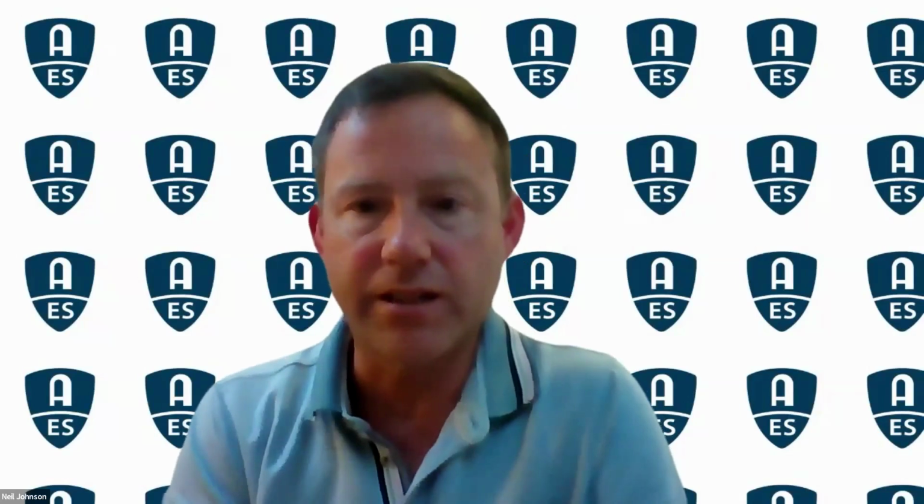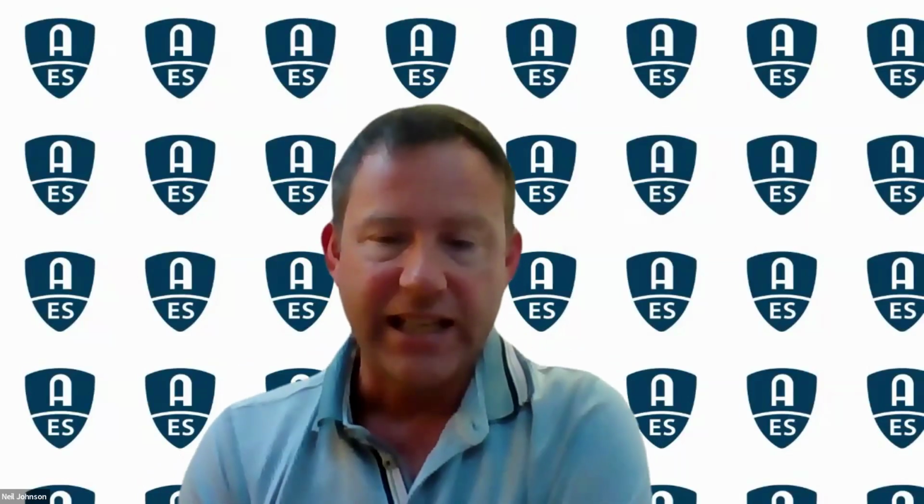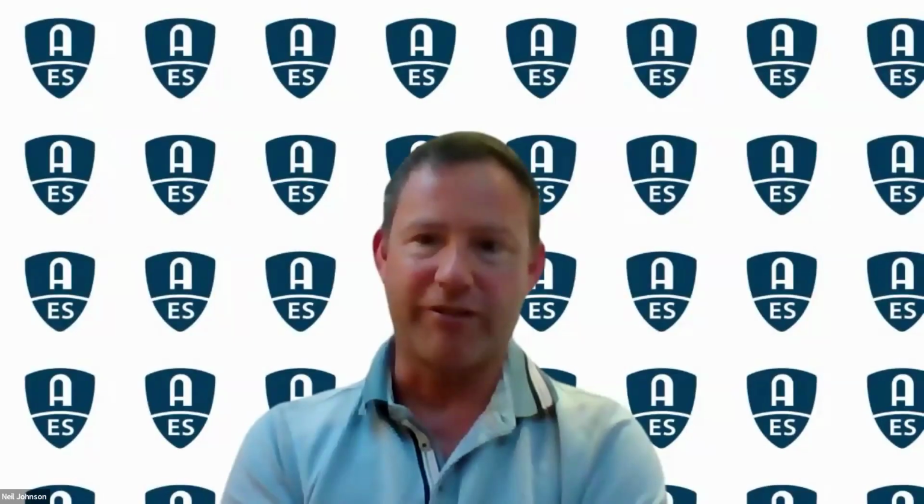And a follow on from Alex's case was the present day VCAs by, you either pronounce it as that or THAT Corp. THAT, yeah, from the original Blackmer. I haven't looked at their most recent ones. I thought at one point they were using the SSM 2016 type topology, so it's a transconductance based voltage controlled amplifier, but I'm willing to be told I'm wrong on that.